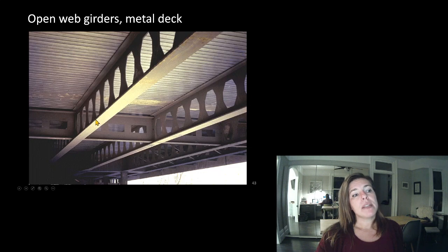Now, this is rarely done. I've never seen it in Canada. In fact, I had never seen it anywhere. I had seen it touted a lot. Our market is labor cost driven. Labor is very expensive in our North American market, and materials are cheap, cheap, cheap, like super cheap. So we will oversize things to save labor costs. You can imagine the extra labor involved in this versus just speccing a beam that's this deep, that's solid right there. For our market, this isn't economically feasible.